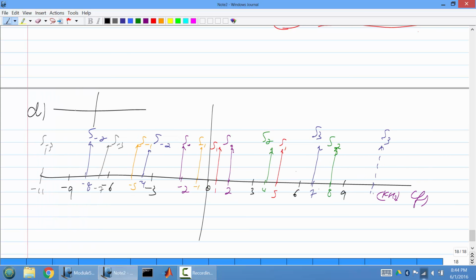My low-pass filter now is, because the sampling frequency is 3 kilohertz, right? I've got to span between minus 1.5 to 1.5. So here we go, right? So that means that if I take this low-pass filter, I have to put it over here this way. Okay, so that means that my signal is actually going to be 2 times S of 1, right? So it's, sorry, it's S of 1 and then S of minus. Yeah, so it's just S1, I guess.